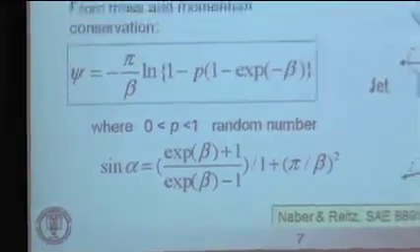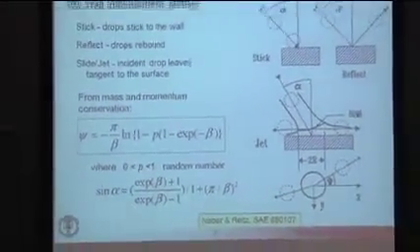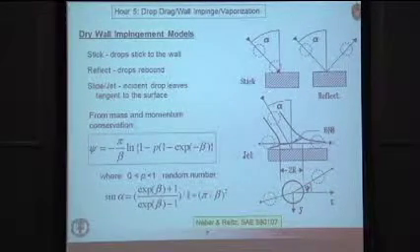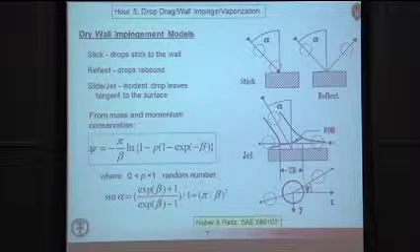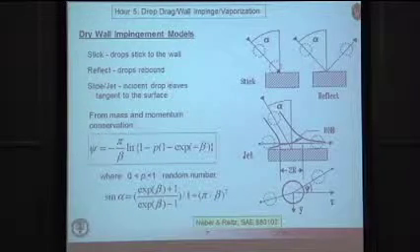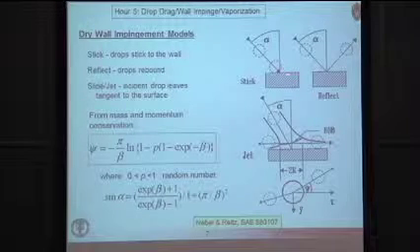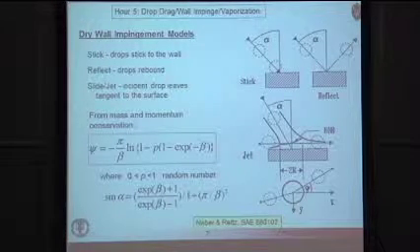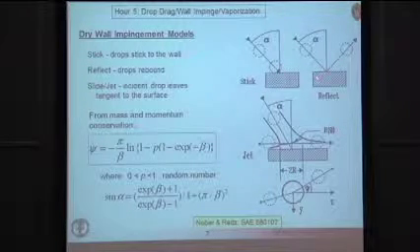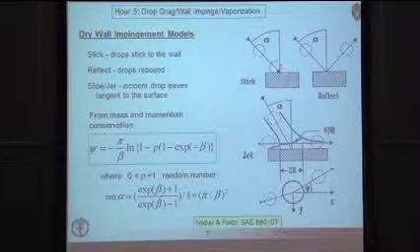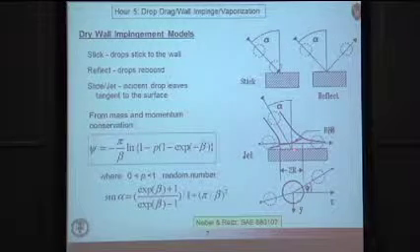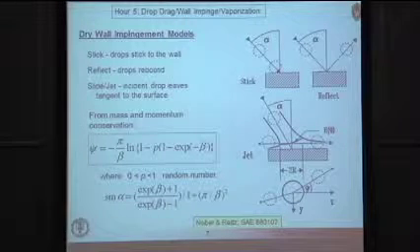So we developed a theory back in the late 80s to describe the various regimes. This is what the guys who use spray painting equipment rely on: if you have low enough incoming droplet Weber numbers, you can cause the droplets to actually stick on the surface. So that's the stick regime. Then there's the regime the spray painter really doesn't want, where the droplet bounces off the wall. And then finally, this is the jet regime. So the droplet approaches the wall and then slides along the wall.